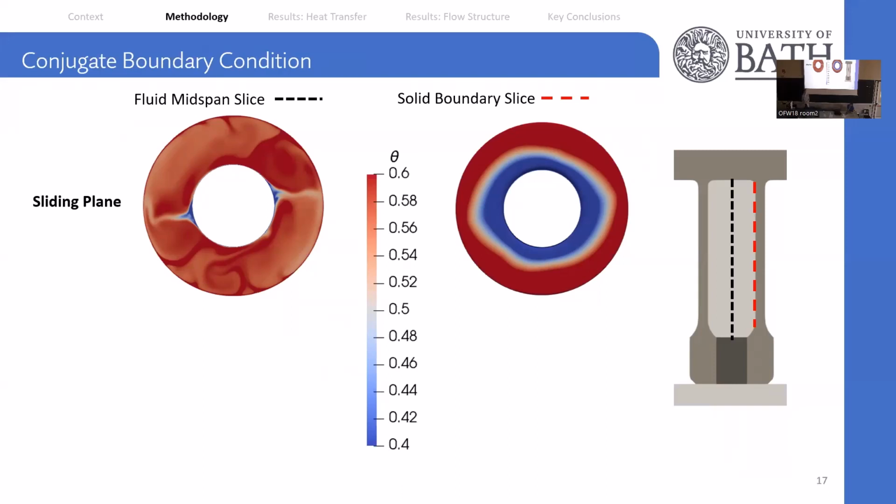And this is because we're using a steady state. But every single time step, the solution is then perturbed as these radial structures slip relative to the rotation of the disks, which means a convergence can never be reached as we constantly perturb the solution.